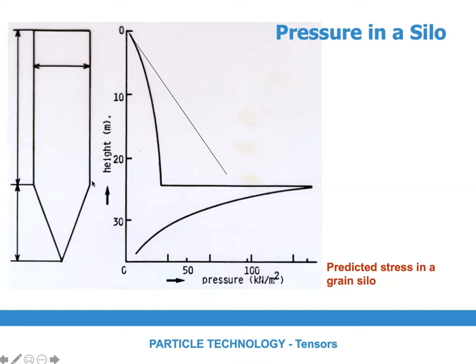So in your silo, you want to design it stable here. Most designs use much less material when you go up, because you see the stress is not getting very high there. But if something happens and one of these force changes kicks the wall here, then the silo can fail. That's the reason why silos fail. A silo with water would have to get continuously thicker from top to bottom.